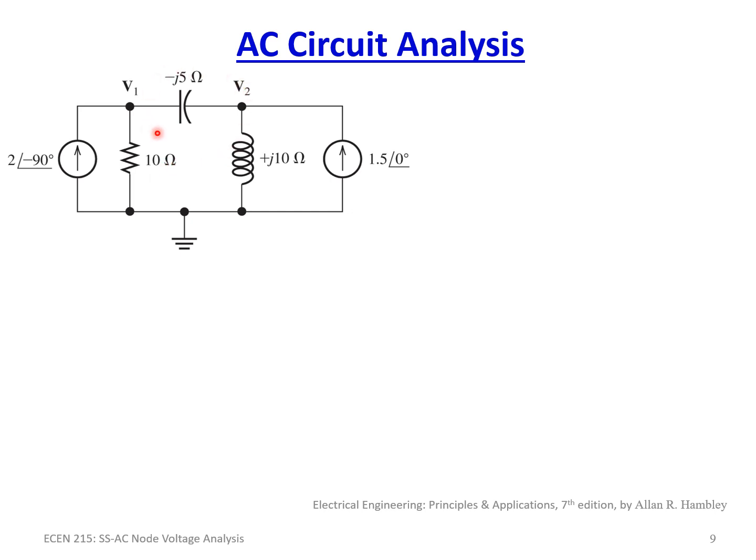So with that being said, let's start the circuit analysis here. Again, I like to do leaving current. That means we're using Kirchhoff's current law for nodal analysis. We've got 2 nodes, V1 and V2, and our reference node, node 0, is right here. So everything being measured, like V1, is measured to the reference node.